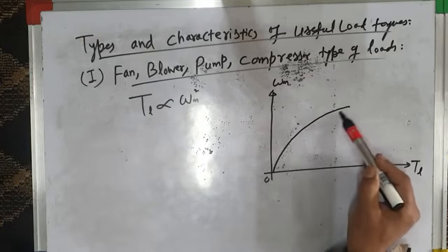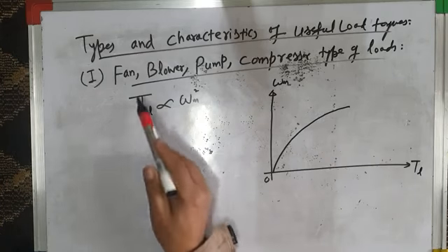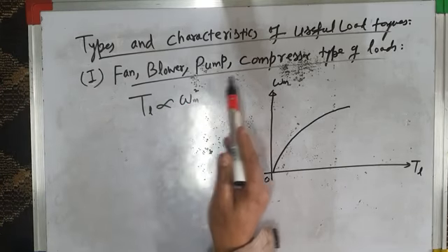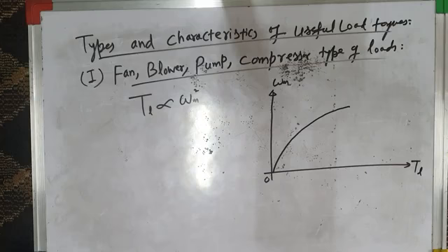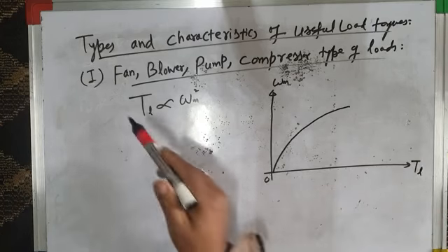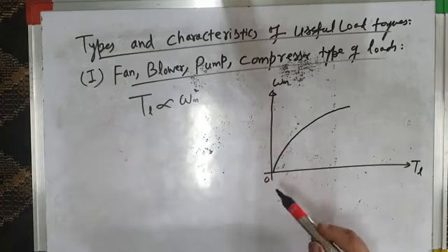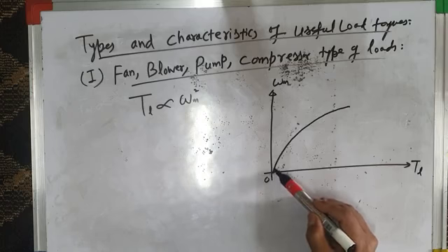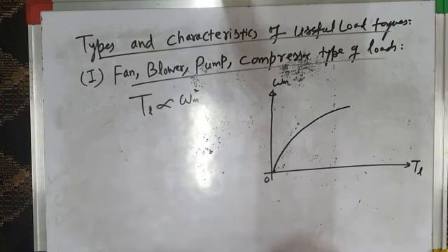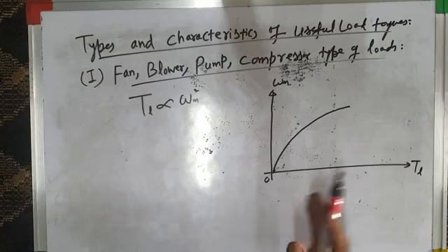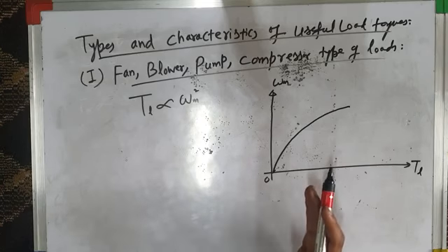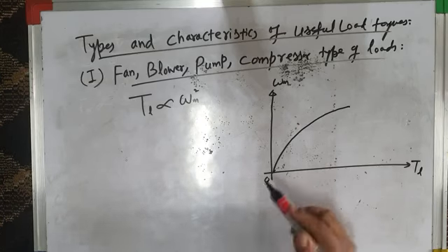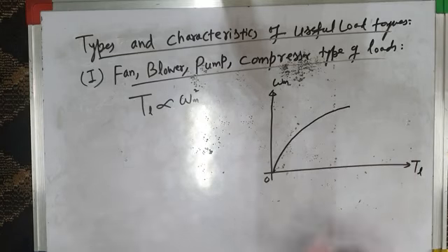So we get this type of load torque characteristic for fan type load, blower type load, pump type load, or compressor type of load. Fine. So therefore, whenever you have to select a motor for driving this type of load, say fan or blower or pump or compressor, whose speed torque characteristics are like this, it will help you in the selection of the proper type of drive or proper motor for running this type of load. Okay, so this is